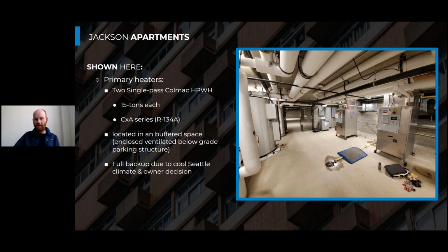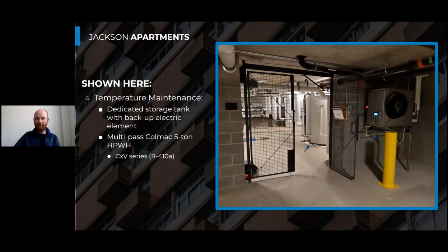If we didn't discharge that air out of this space, these heat pumps move around 6,000 cubic feet per minute, or CFM, during operation. So that's a lot of air that's being moved. We would actively cool this space down because that air would be short cycled, so we need to duct it out. That's one of the important designs of these heat pump water heating systems, getting that cool air away from those heat pumps.